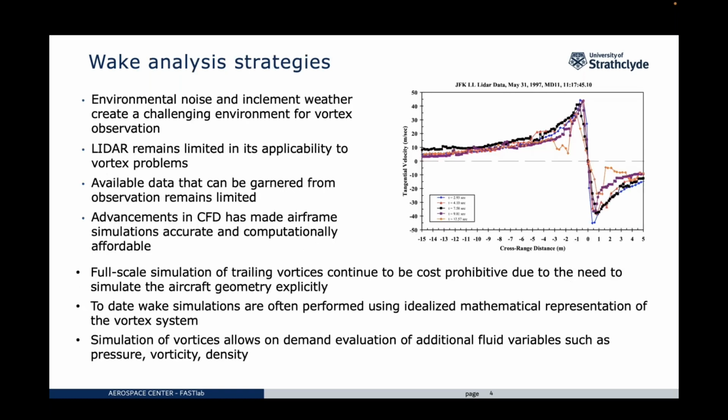So before we get to the new methodology, there are two ways that we can analyze wake vortexes. There's the experimental side, and that's things like LiDAR technology for in-field measurements around airports, or PIV and pressure taps for measurements inside wind tunnel experiments.